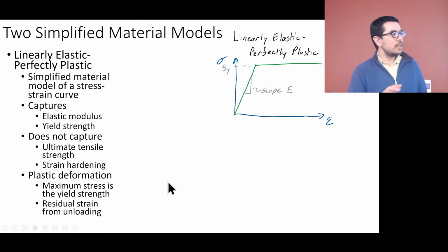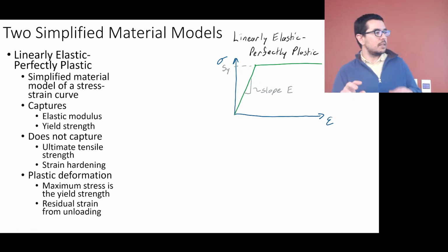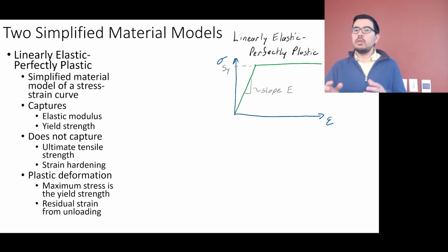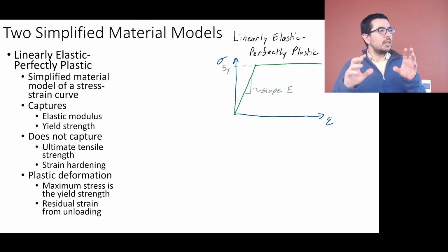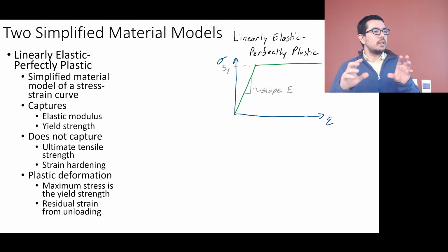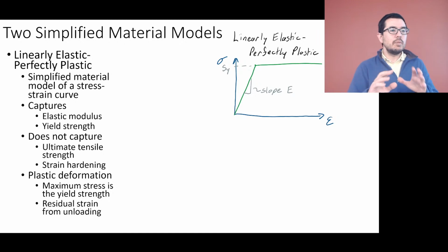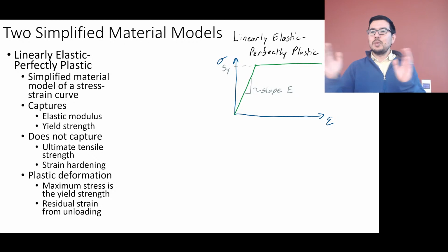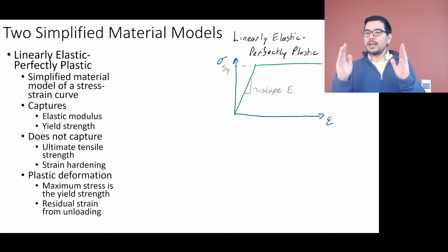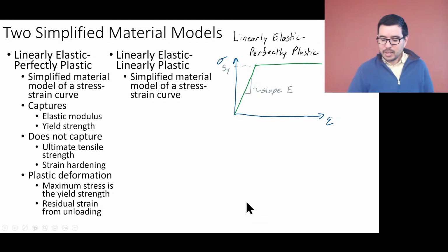Okay. And when you take the design of mechanical components, you'll start to look at how the geometry permanently deforms with embedding of residual stresses and residual strains. But we're not going to cover that except in the axial case. If I stretch a bar beyond its yield, it's not going to go back to its original length. And we can calculate that, and we'll show that.